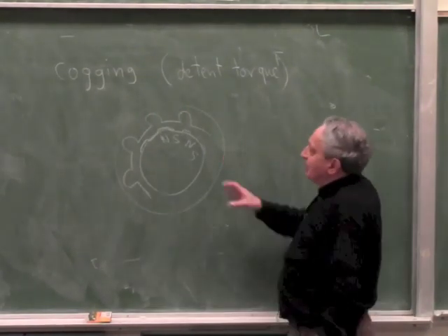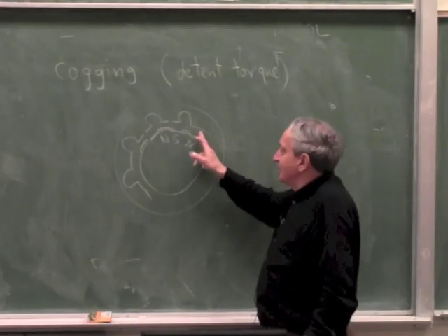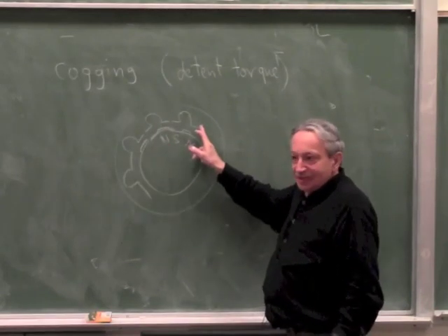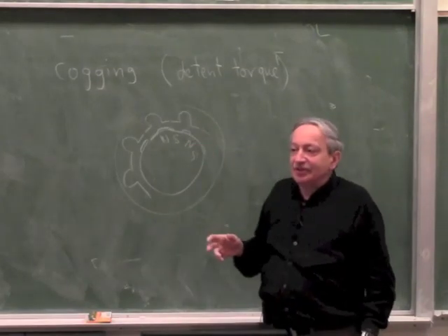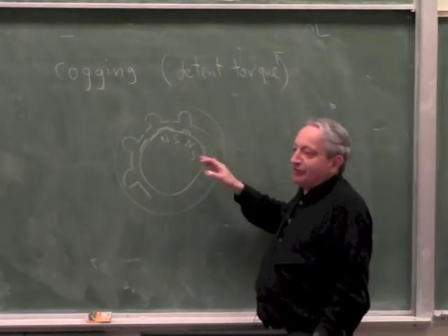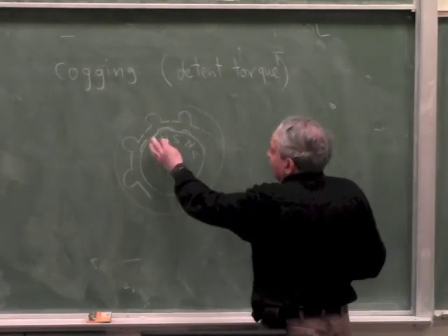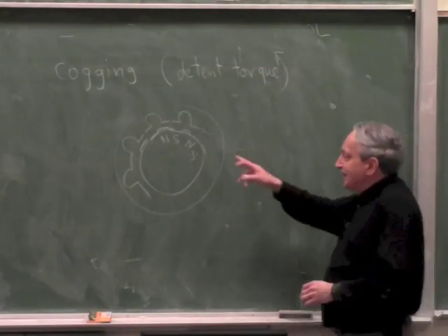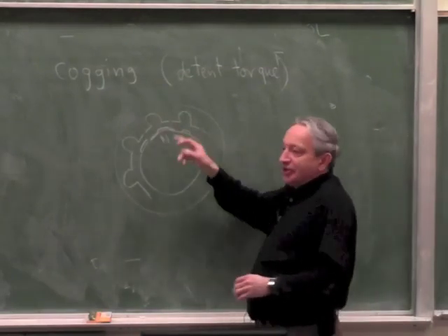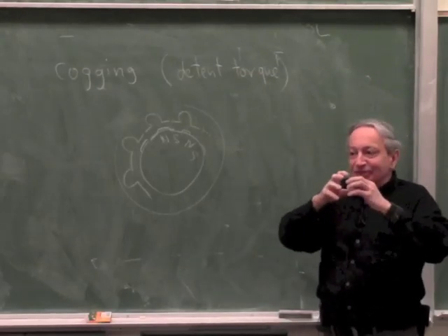And I mentioned there is some natural detent position where the magnets like to line up with these salient poles. Okay? Now, when you drive it with a rotating vector, if the flux distribution is perfect and the coil arrangement is perfect, it will just rotate smoothly with a vector. But you still can see the signature of the detent, of the positions it likes to snap into.